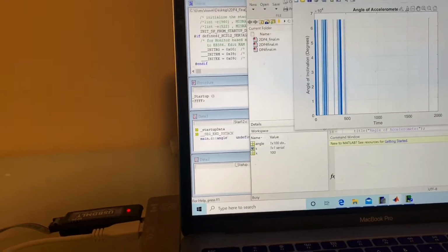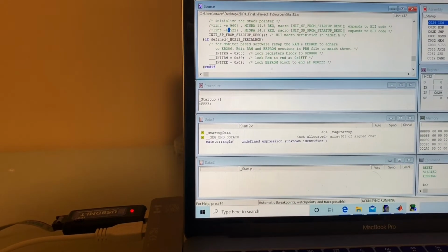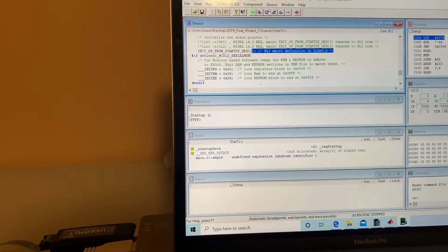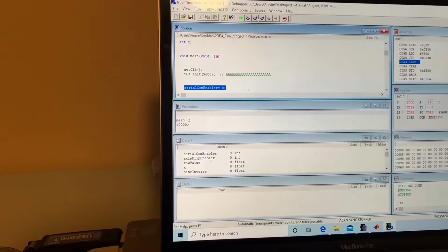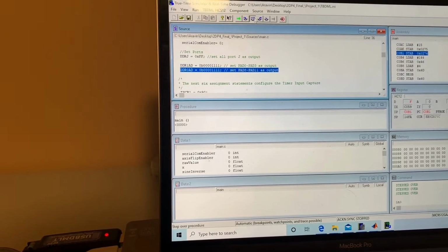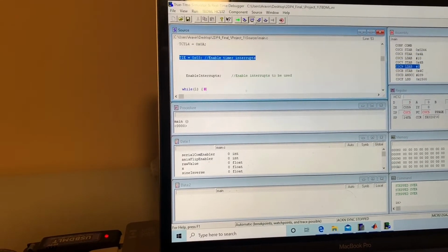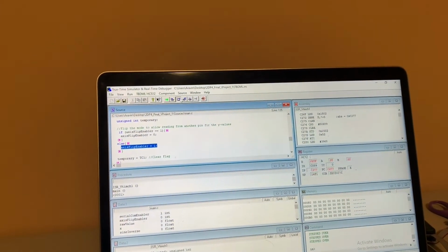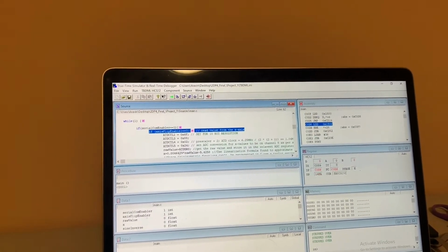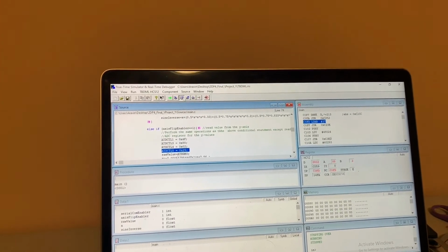As a quick run-through, I can run you through all my code very quickly. As we step through, we have initialization, the main function, 9600 as I mentioned before, and the serial communication, with all these parameters being set up. I'm going to step through this very quickly because I know I'm over time. Then I'll show you that as I press the first button, we initialize the first interrupt, which is exactly what we want, the serial communication enabler. The second button is pressed, and it jumps to the axis flipper, which is perfect. Then we do the corresponding calculations, which are all done here.